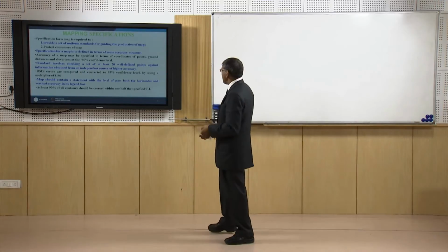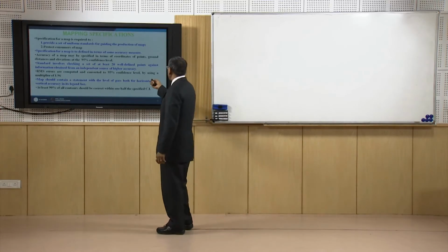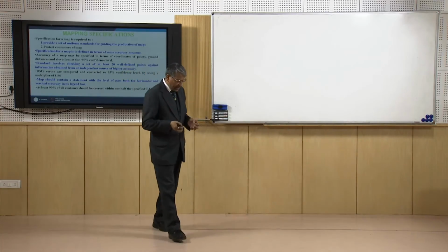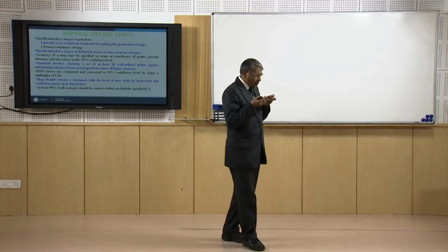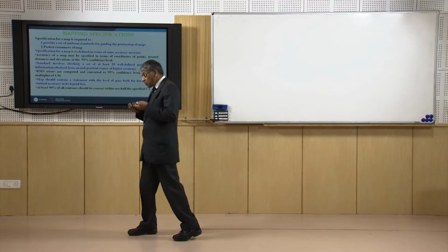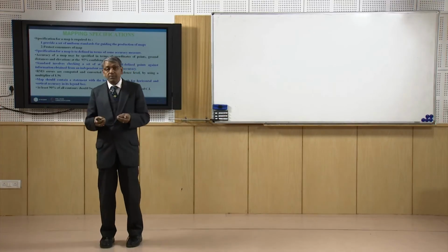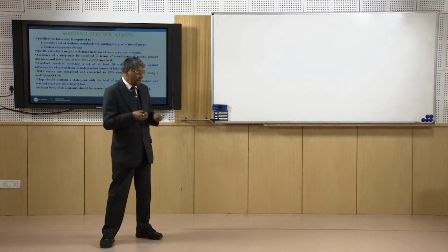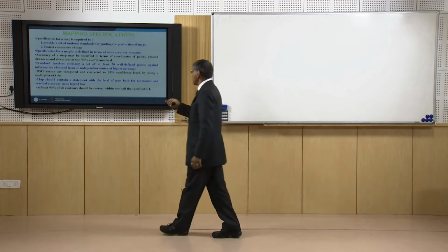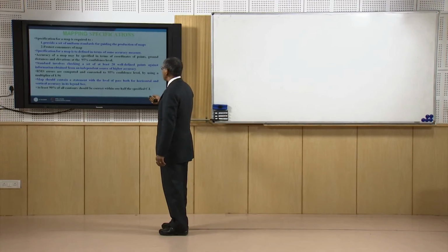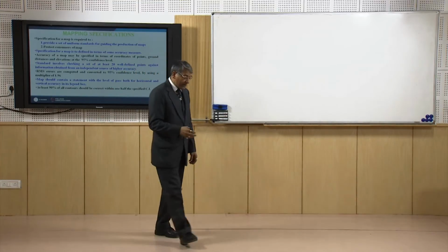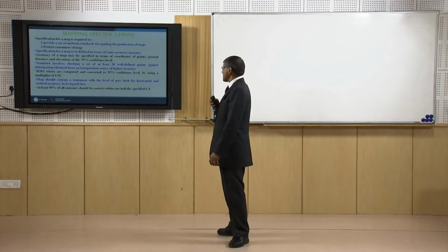These are the basic elements: points, ground distance, elevations, which we try to represent in a map, so we should define an accuracy measure on these elements, and that accuracy measure is that it should have the 90% confidence level. I have already discussed confidence level and accuracy in our previous classes.